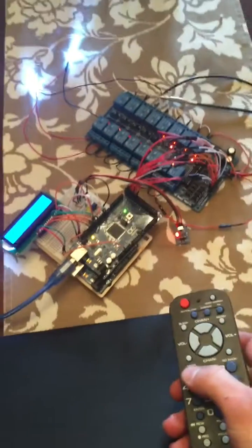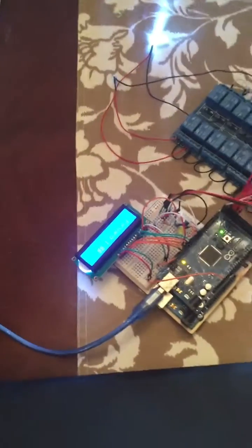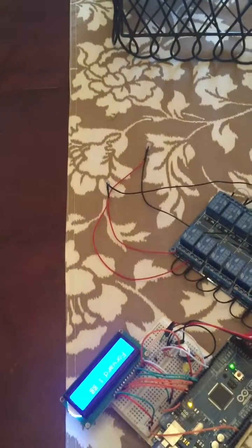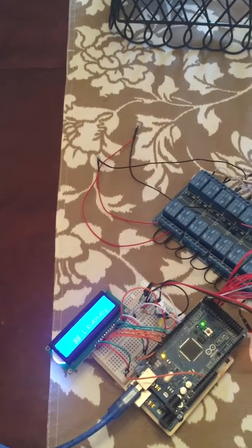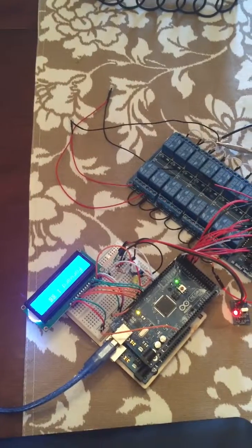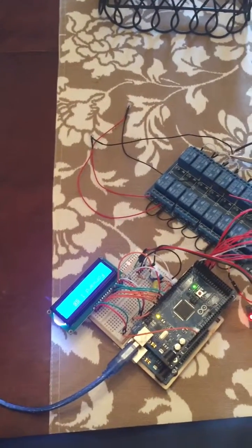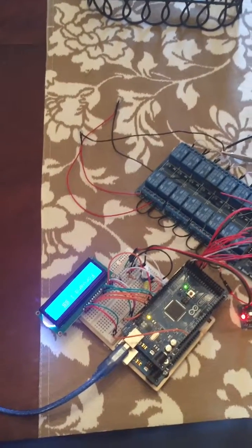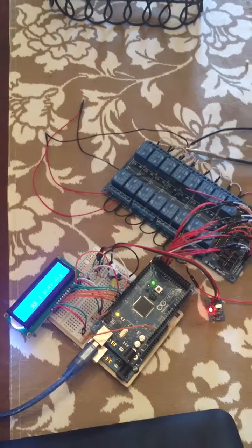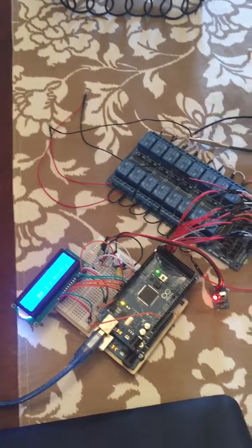So if I go ahead and hit 1, our lights flicked there. The way I have it set up is it's going to kick the transmission into neutral for 500 milliseconds. It's going to turn on the solenoid to shift the transmission into first gear, then after 2 seconds shut that solenoid off, because in my trainer it's using air solenoids and they don't need to be on for the duration